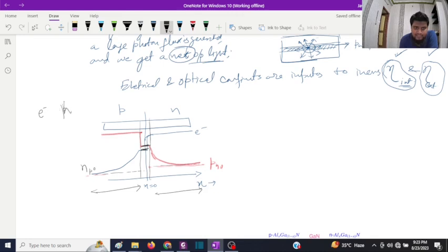And that's why, if they exist in almost equal numbers, then it will be maximum. The lowest concentration decides the rate of recombination; the highest concentration does not decide. So in the junction region, light emission is most probable, and of course it will be generated.